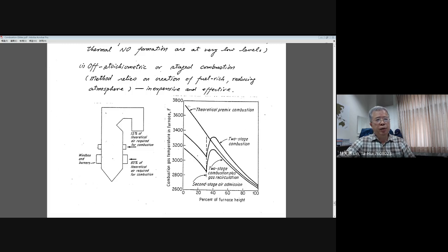Okay, then the temperature will continuously reduce. This is for the single stage burning. Now, if you choose the two-stage combustion, the temperature variation will change. Initially, since the first stage is under rich conditions, the temperature should be lower than the previous one. This is a small temperature variation.